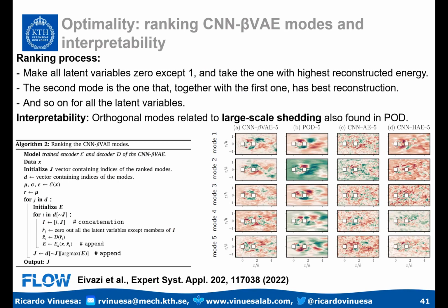Here you don't separate into large and small scales. The strength of the autoencoder is that you're compressing the data into modes that incorporate that range of scales into one particular coherent thing. If you want to do the analysis of separating scales, that's not something that you can do. That's not the right tool to do that, basically. You would have to use POD or something else. If you want to look at temporal scales, you can look at DMD.